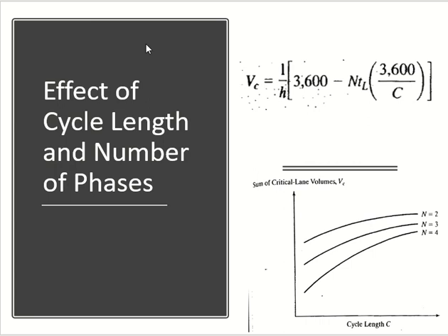Okay, but why these limits are given? If I can just keep on increasing the capacity with the increase of cycle length, then what is the problem with them? Why would they have a problem if I am getting more capacity? The problem is more cycle length means more waiting time as well. So when you increase the cycle length, you will increase green time as well, right? You increase my green time, I'm in one direction, right? That means what? My green time increases, for others, red time increases, right? When I have green, they have red, right? So my green time increases, their red time increases, okay?